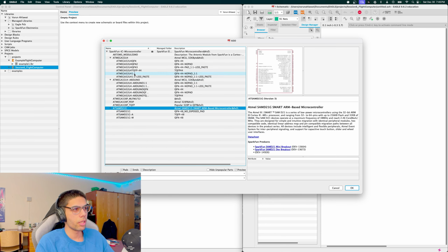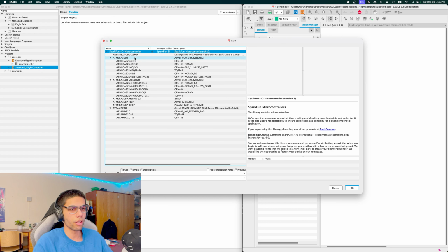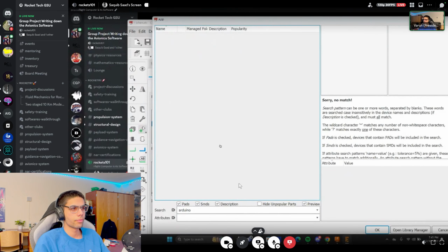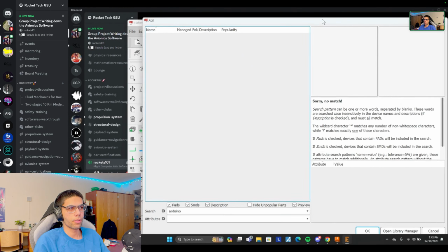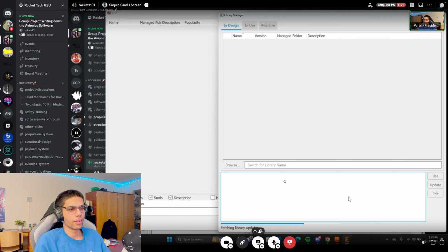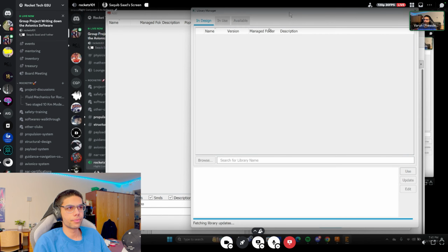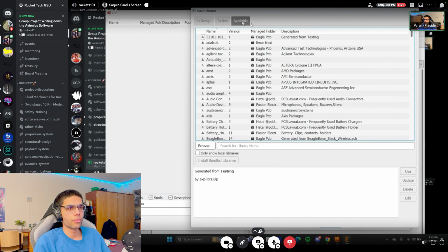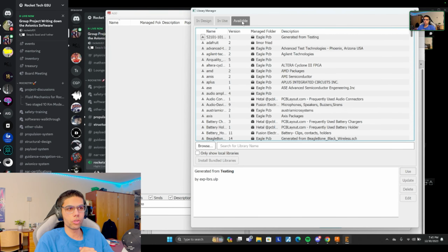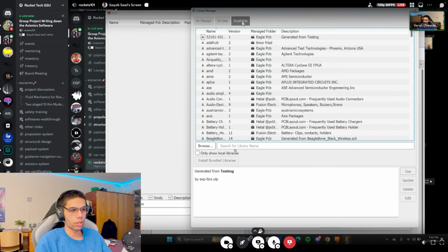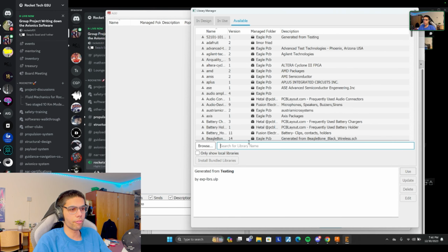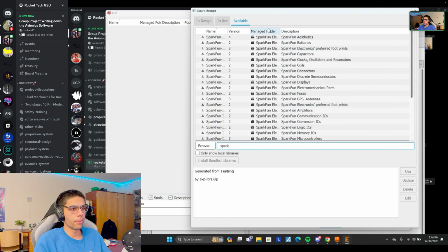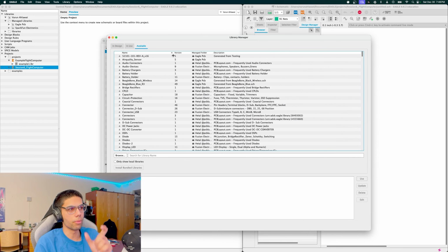I am seeing these because I have installed this library, but can you share your screen and search? You are not going to see any of these. Now open the library manager. Now go to the available tab. This is the browser that I was talking about. These are the libraries on the internet, not on your PC right now. You can search for SparkFun. Increase the width of the name column.